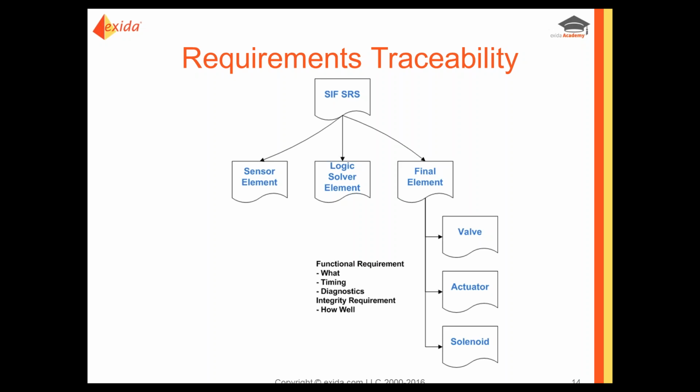But then the functional requirements: what does the system need to do, what are the time requirements, what are the diagnostic requirements, what are the integrity requirements, such as what SIL level does it need to meet. All of those requirements need to be traceable down and applied as appropriate to the devices that go into the final element, and then also be able to be validated coming back out of that integration step to show that they've been met.